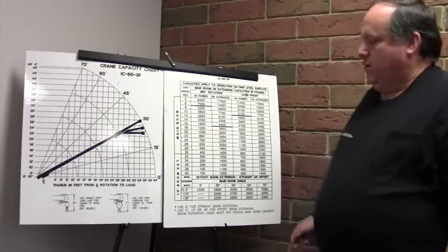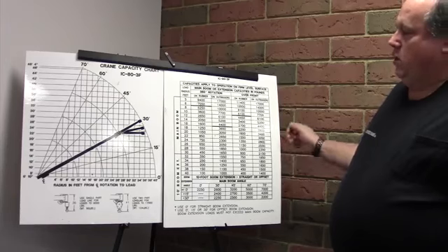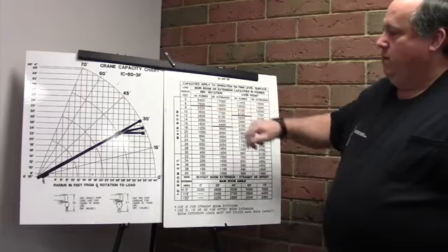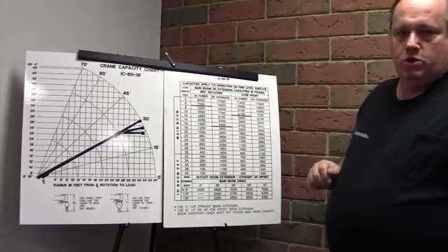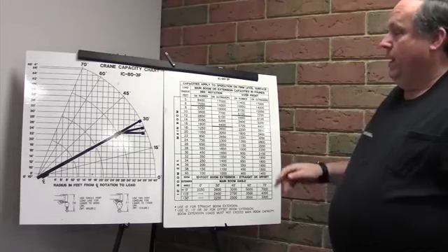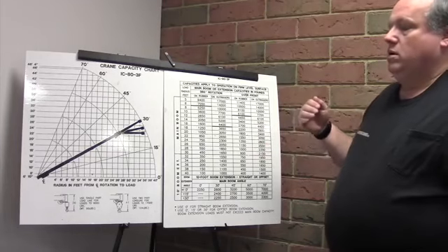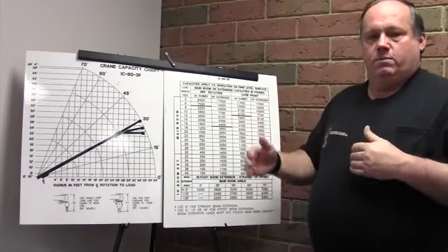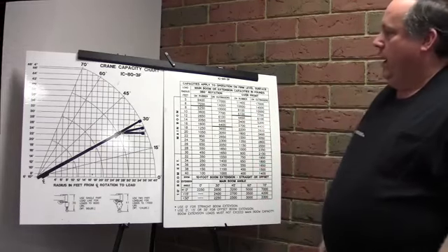So that's just a basic overview of how a load chart is used. Remember once again that when you're above the black line, we're limited by structural capacity. When you're below the black line, you're limited by tipping capacity. And so you don't want to invade that safety factor that you have of 15%. So never overload the crane, and you'll always have success in your lifting operations.